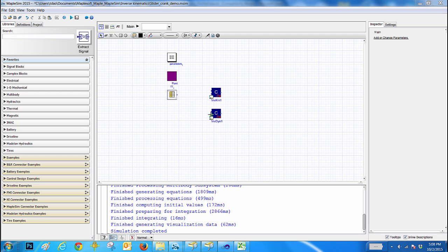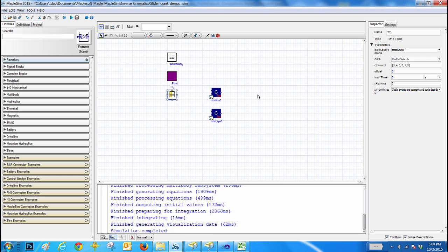So now I have the two MapleSim custom components for inverse kinematics and inverse dynamics. I can go ahead and do a few tests and then compare the result with my simulation result from my main plant model. In order to do the test, I would need to use a profile that was generated based on the previous run of the plant model.